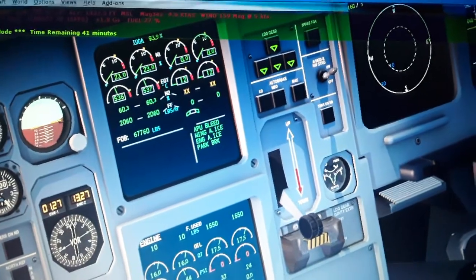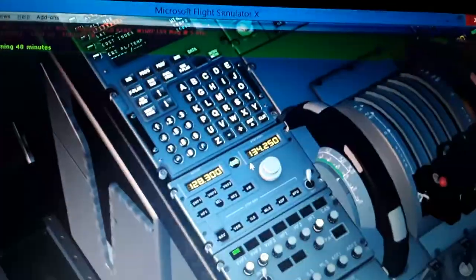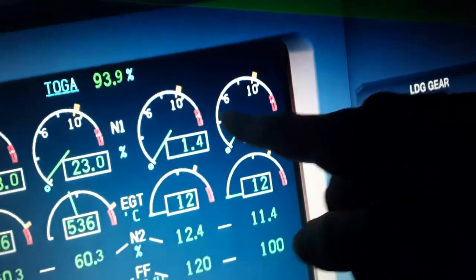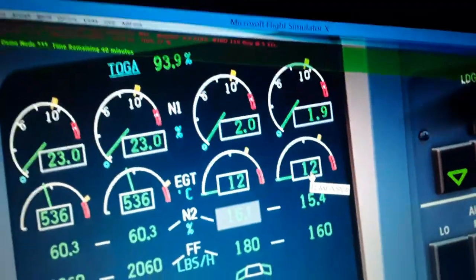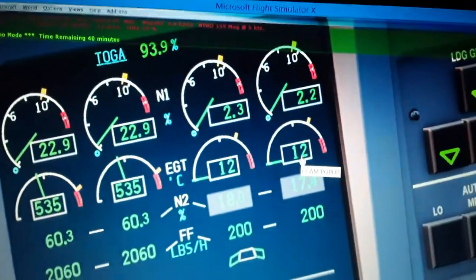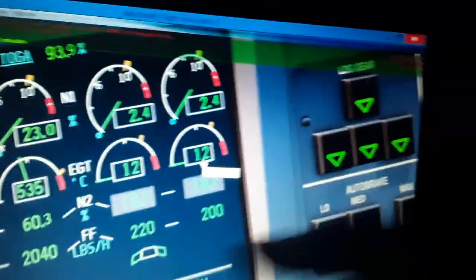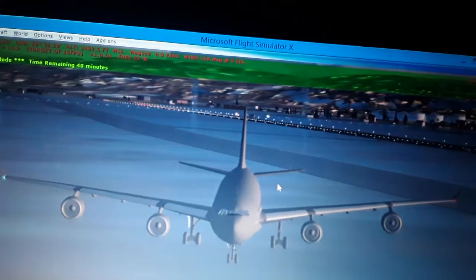So we go with the other side now, engine number 3 and engine number 4 here. So you can see here the right wing engine going on. After 20% N2, the fuel flow low and high pressure valves are going on.